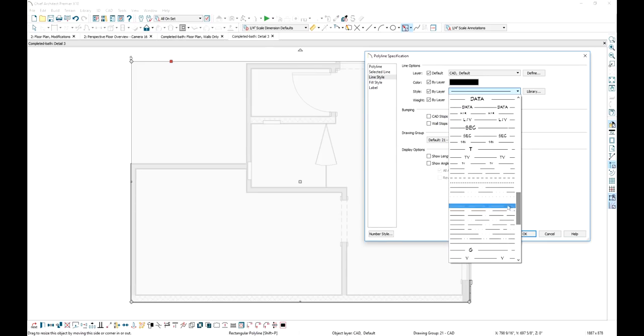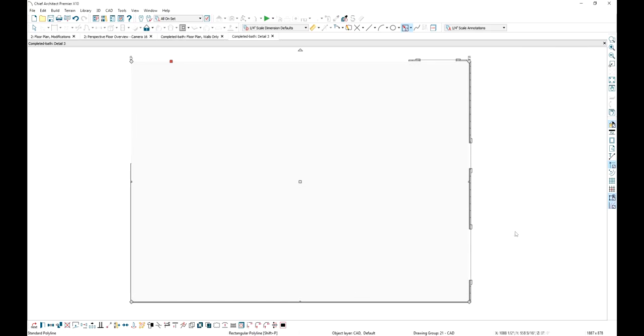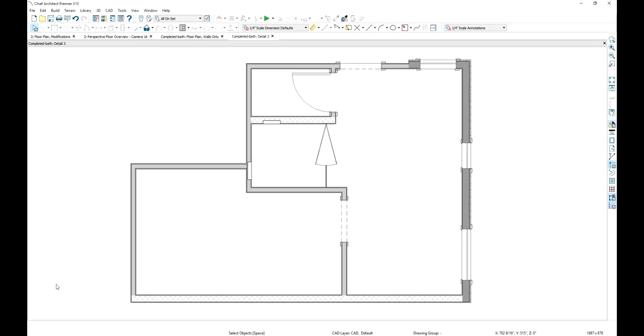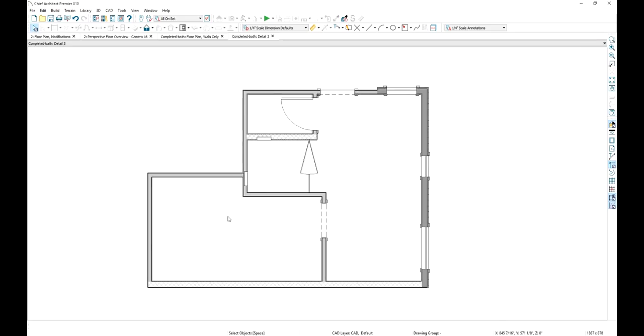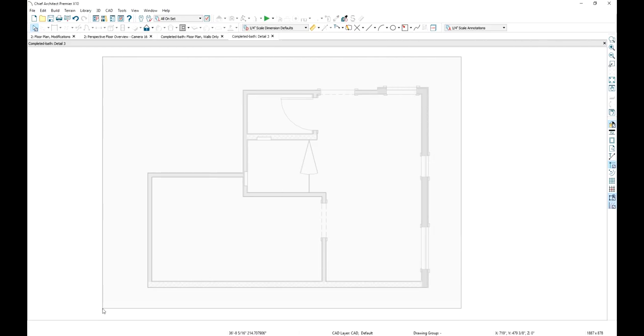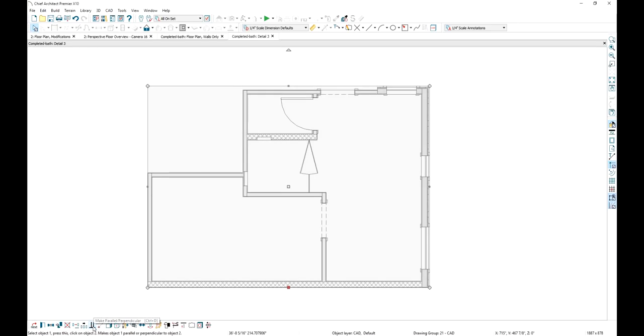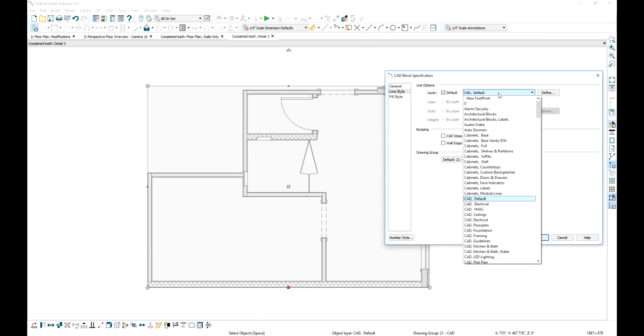With the fill style complete, let's use the draw order move, and we'll send that to the very back of the draw order, and now you can see over the top. And what I've done here is I've created a mask that will hide the underlying walls when we paste this into the other plan. Holding my Shift key down, let's just draw a marquee right around the outside of this. I'm going to create a block so it makes it easy to move and manipulate. Once it's a block, let's go ahead and open it up, and I've created a layer for it called the New Plan Footprint.